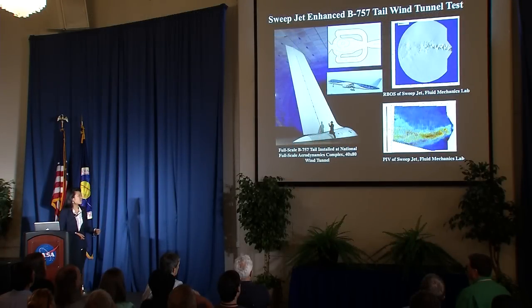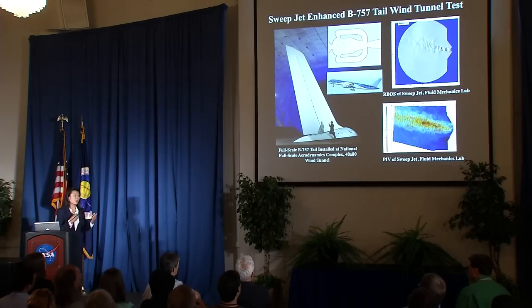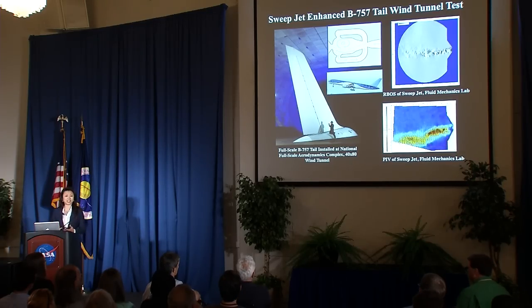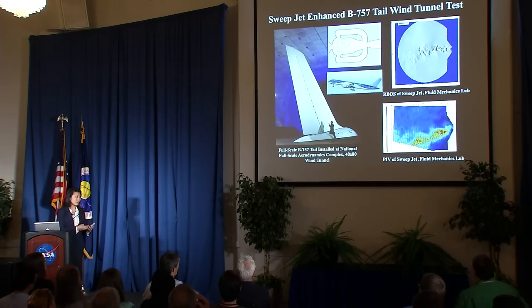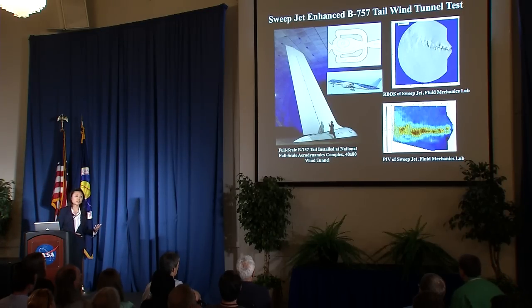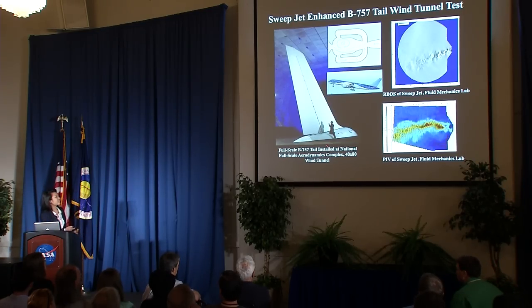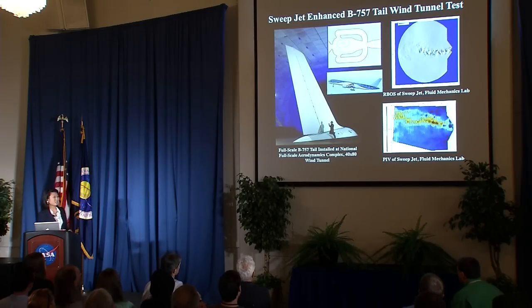Because these are installed, it provides 20% more side force, which results in we don't need tails that big anymore for the plane to fly. So we could reduce the size tremendously, therefore reducing mass and drag and giving us a more efficient plane. This was a successful test, and they actually tested it in flight in April 2015 on an eco demonstrator right here. And that was also a successful mission. I expect to be seeing this flow control on all future planes.